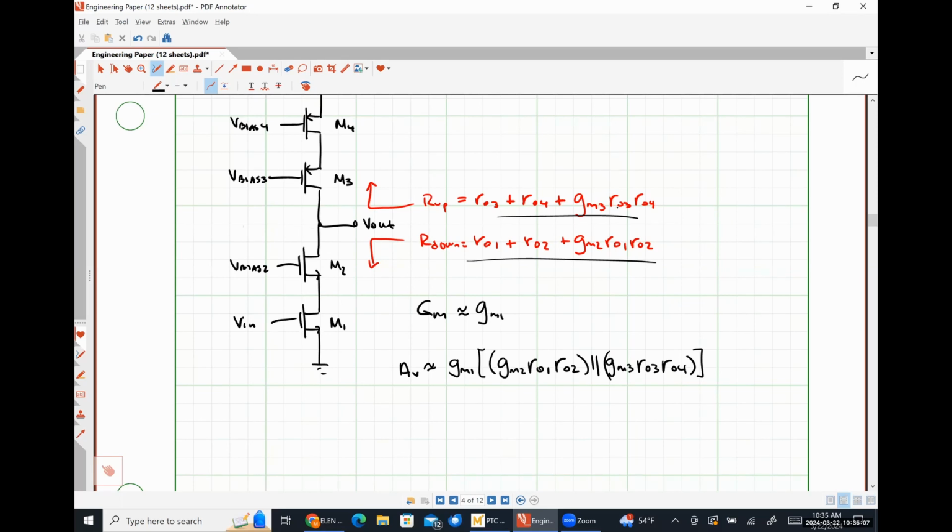One interesting thing about a MOSFET cascode is, particularly in integrated circuit design, we don't have access to really changing mu n, Cox, and all of that kind of good stuff, but we have the ability to change our aspect ratios, which in turn can change our transconductance and all of those kind of good things.